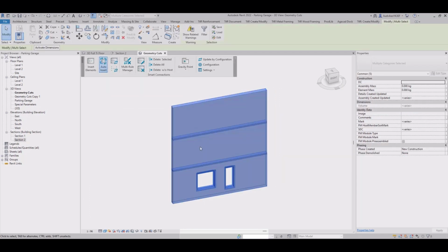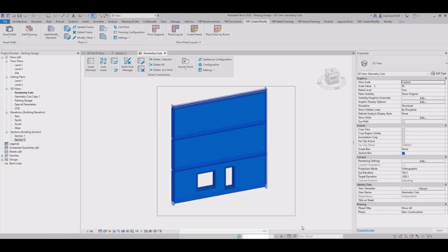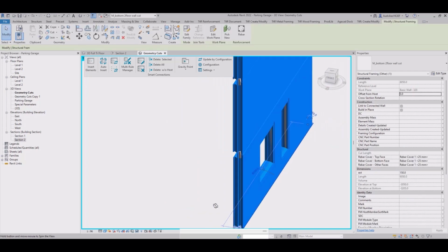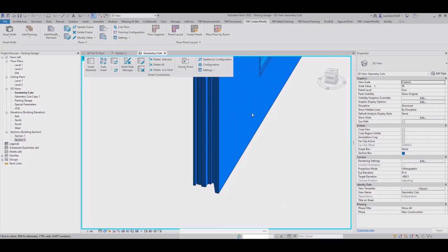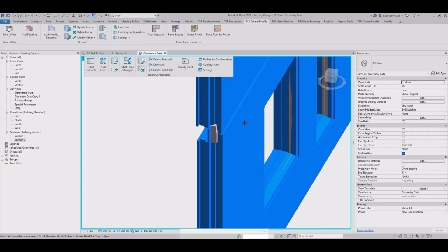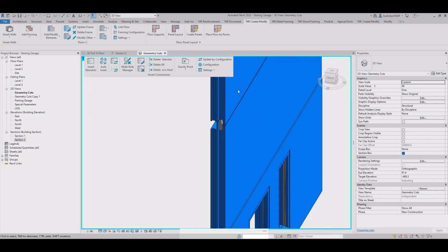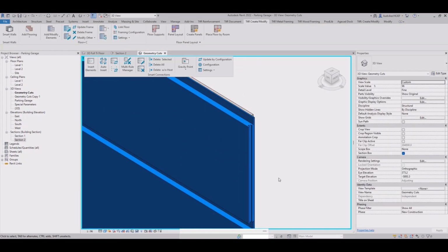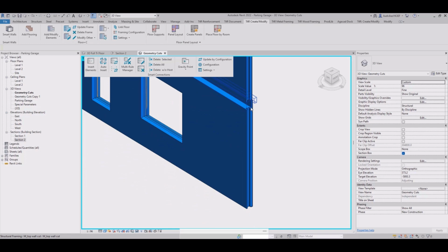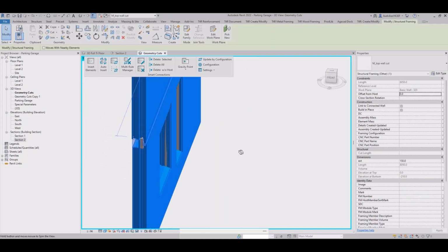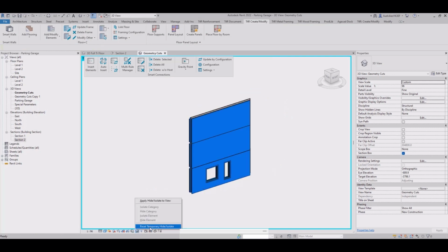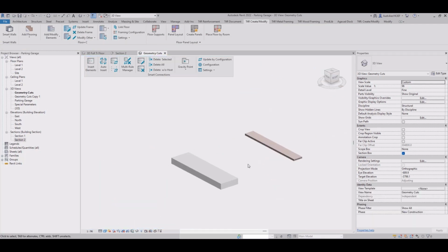And for example, here I have 3 walls that I want to modify, and I added cuts from the sides for top and bottom. Also have a concrete fill between the walls, and this is how we can get the exact volume and geometry using Smart Connections. Simply, we have these with native Revit designed families, and we can use Smart Connections for different kind of system families and line-based families.